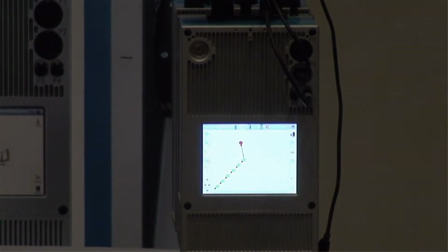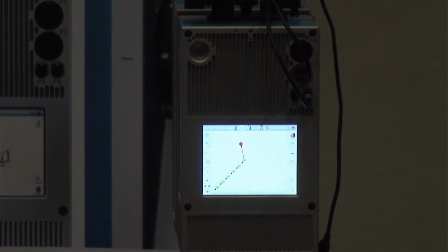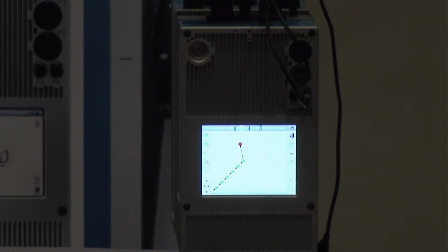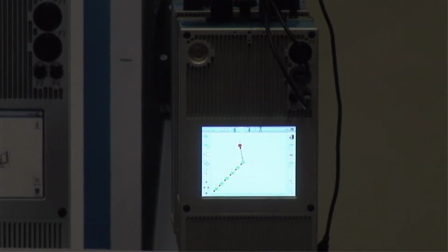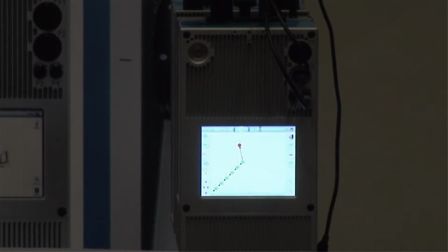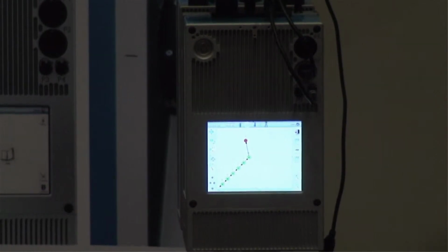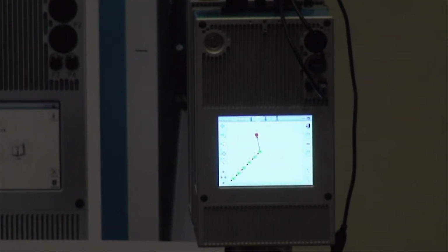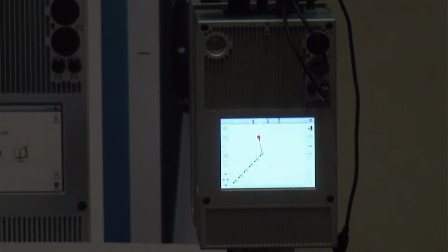After you did the entire project, you can see an outline of your object, of your site, and you know exactly where you scanned before. So it's quite important if you scan, for example, a building, you start in the morning on one side, you come around, and in the evening you're at the other side. Or you join the project together again.